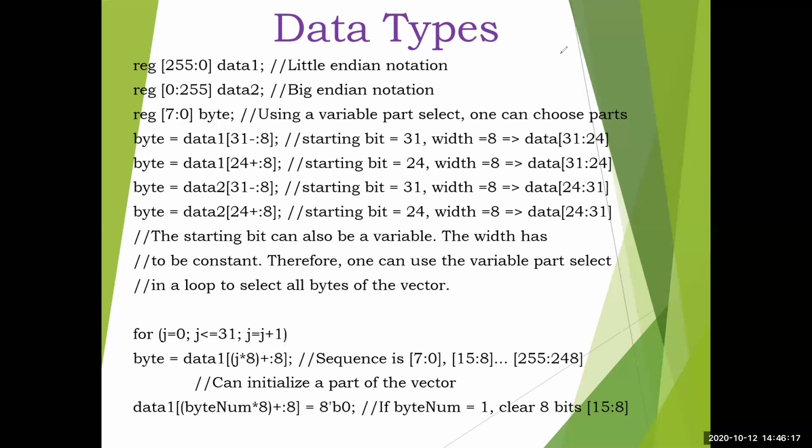So this is it regarding the first part of data types. We have seen the value sets. It will have 4 values 0, 1, x and z, and then 8 different strength levels, strongest to weakest. And then we have seen the data type nets. It will be declared using the keyword wire. Default value is z, and a driver should be connected to the output of that.